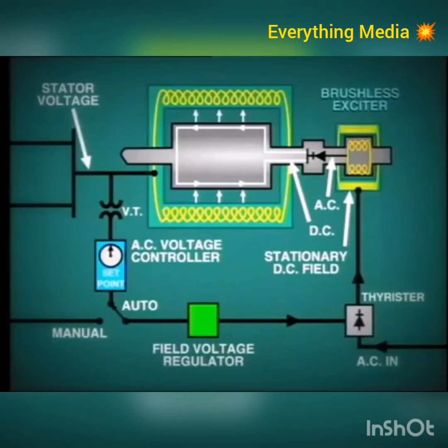Control of the DC excitation current is effected by adjusting the strength of the exciter magnetic field, and this is done by controlling the DC current flow through the field winding. This DC field current is supplied from a rectifier which is located in a nearby cabinet. Of course, this rectifier is much smaller than the static rectifier that we previously studied, because it is only supplying field current to the rotating exciter.